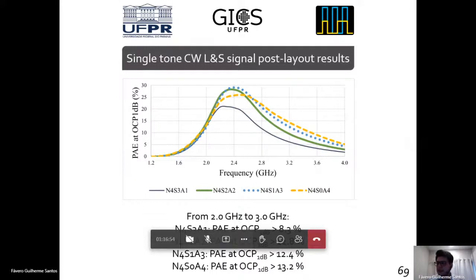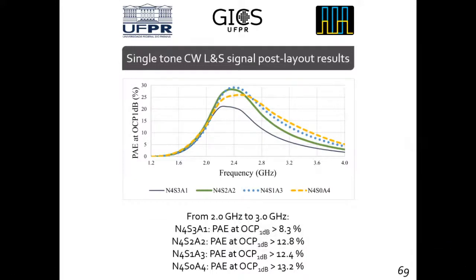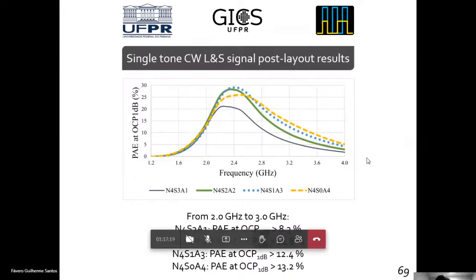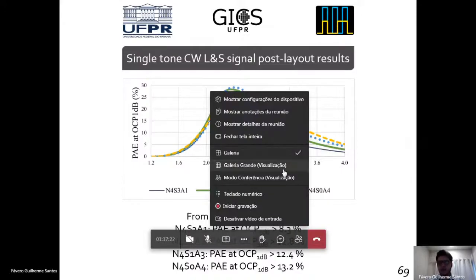When I was designing the power amplifier, I actually tried some wideband matching networks at the input and the output to observe if we could somehow achieve wideband operation. So I believe if we change the input matching and the output matching with other types of circuits that allow wideband operation, it would be possible.